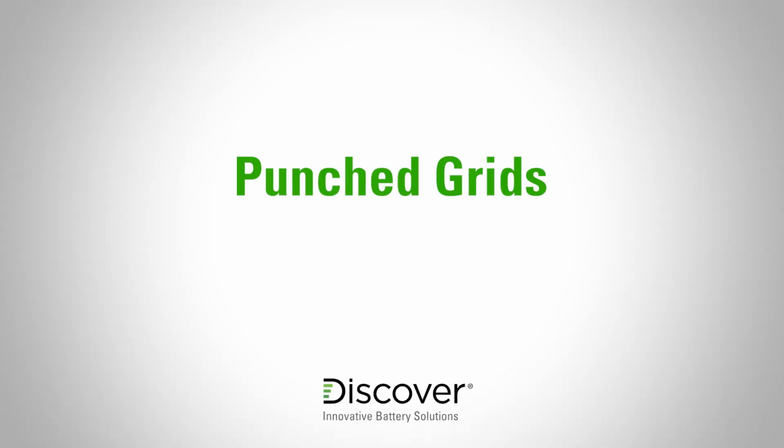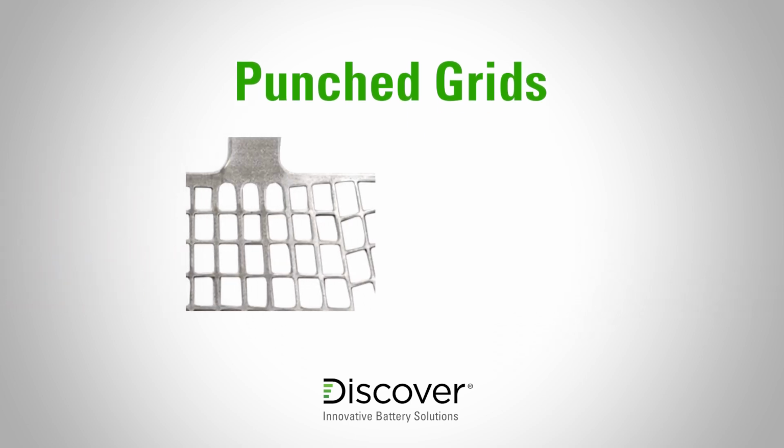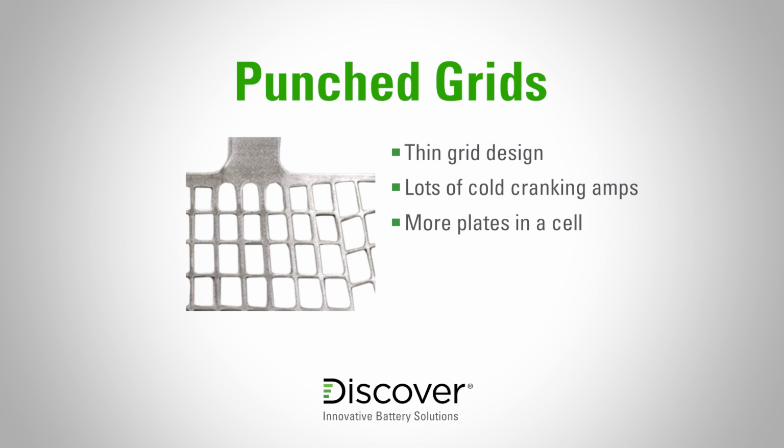Punched grids, so the grid that probably or arguably is produced at the highest volume and at the highest rate, allows for real thin grid designs, for lots of cold cranking amps, because you can get lots of those plates in that particular cell. It's a stable design in that it's a full frame grid, but you can't get as much active material onto that full frame grid as you can with an expanded metal grid.